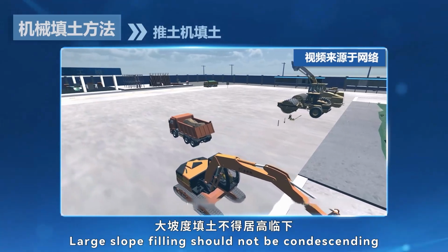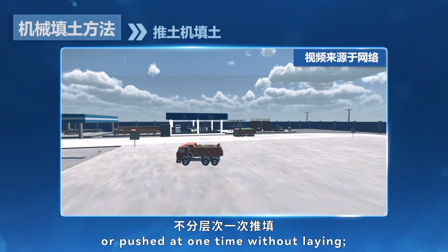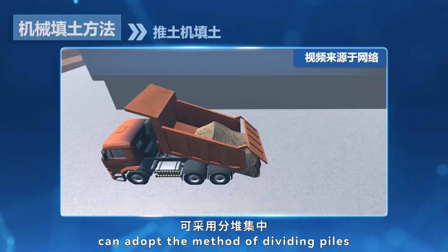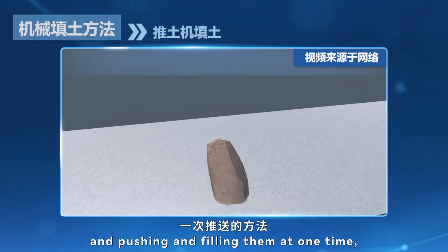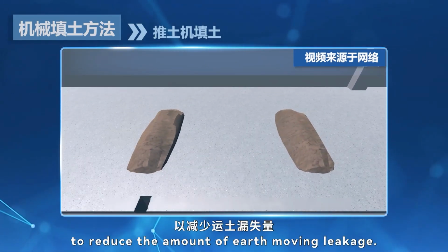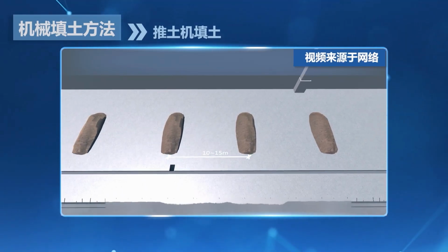Large slope filling should not be pushed at one time without laying. Bulldozer earth moving and backfilling can adopt the method of dividing piles and pushing and filling them at one time, with a segment distance of 10 to 15 meters to reduce the amount of earth moving leakage.